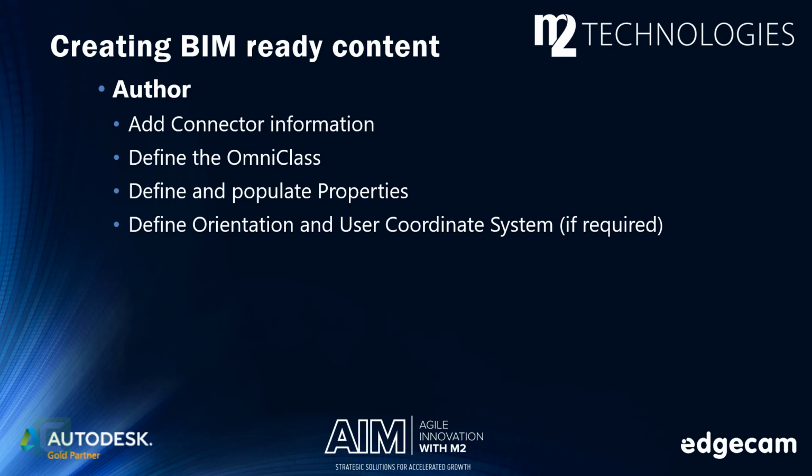And then the UCS or the orientation that we need to set up, that has to be changed based on the fact that the AEC industry uses Z as up or down, whereas the manufacturing industry uses Z as near or far.